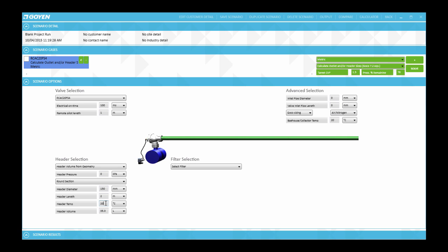There will be cases though where the location of the header tank will be immersed in a hot or cold environment or close to a heating or cooling source, thereby raising or lowering the header temperature and of the fluid inside, namely the air temperature. The effect of higher air temperature in the header for a given pressure and volume lowers the density of the air, so for a required mass flow rate, the air consumption will be greater.